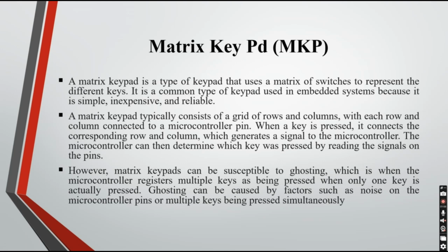However, a matrix keypad can be susceptible to ghosting, which is when the microcontroller registers multiple keys as being pressed when only one key is actually pressed. Ghosting can be caused by factors such as noise on the microcontroller pins or multiple keys being pressed simultaneously.